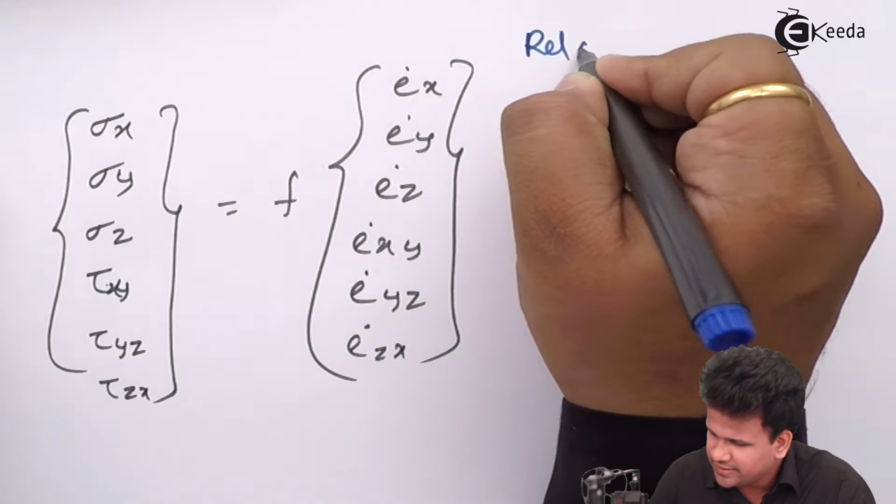Now the second term which we have to differentiate, that is with respect to y. So we'll check this out. So this will go inside. So this will be μ into ∂²u/∂y², and this will be ∂²v/∂y∂x. So let us write down this part. So this will be plus μ will be outside, so this is ∂²u/∂y² plus ∂²v/∂y∂x.